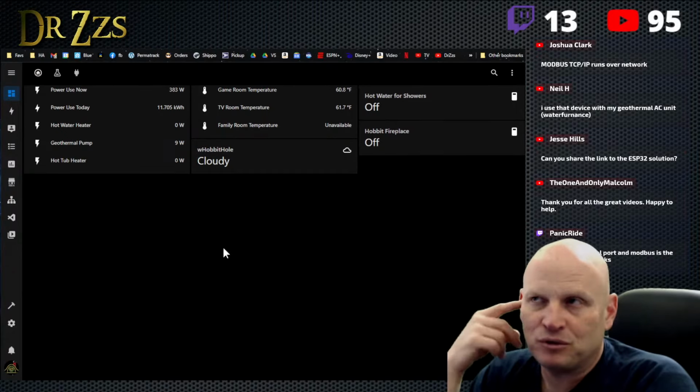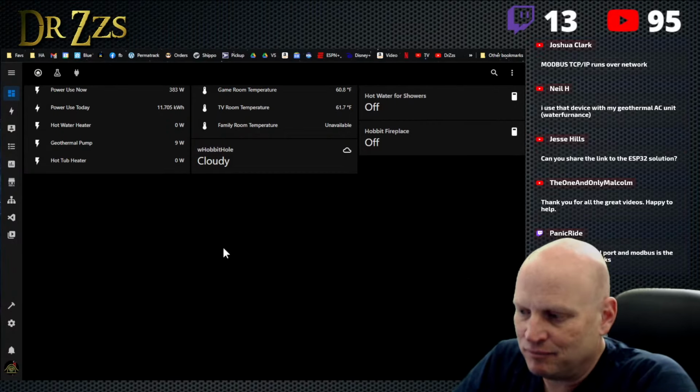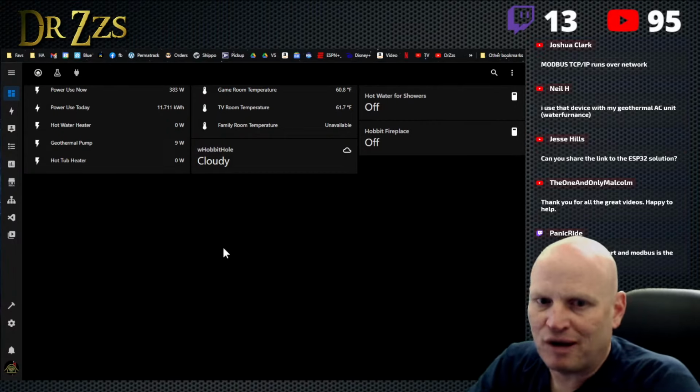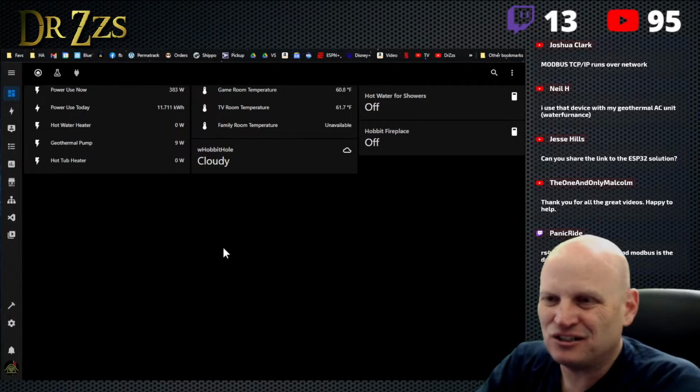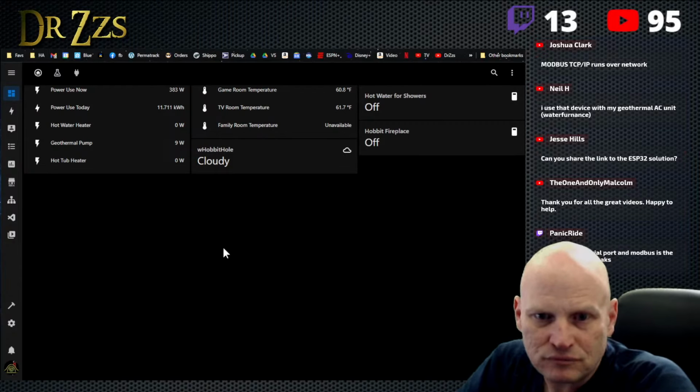So next time I'm up there, which will be this coming weekend, I'm going to have to adjust again the upper end of the voltage drop off. I probably need to just lower it and then test it again and see if it'll drop off at a lower level. It turns on and it just never turns off.